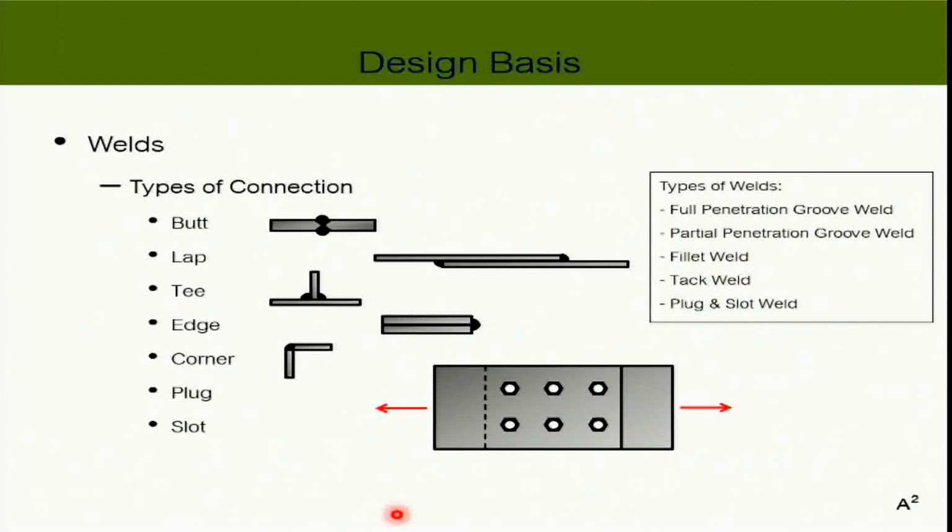safe. No. And right now, the big construction companies prefer bolts to welds because the quality of the bolts can always be controlled if you buy good ones. You don't have to worry about that. But the quality of the welds will depend on, of course, the welders, right? But welds are good in many ways as well. If you somehow need to transfer a very huge amount of force, you can always use that full penetration weld, right? It's going to be stronger than bolts, of course, but it's going to be more costly as well.